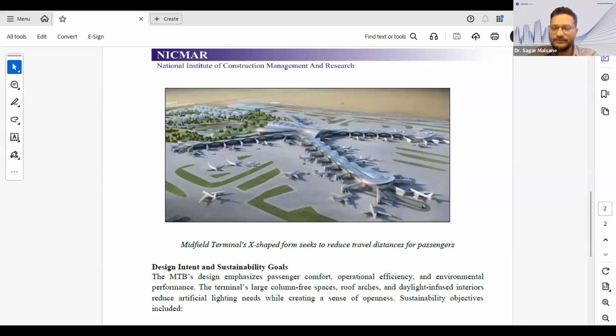For that, there's a concept called BIM execution plan, and you can also refer to ISO 19650. ISO 19650 has been particularly designed for establishing individual roles and responsibilities and having uniformity in terms of work allocation, so that common standard uniform practices can take place.